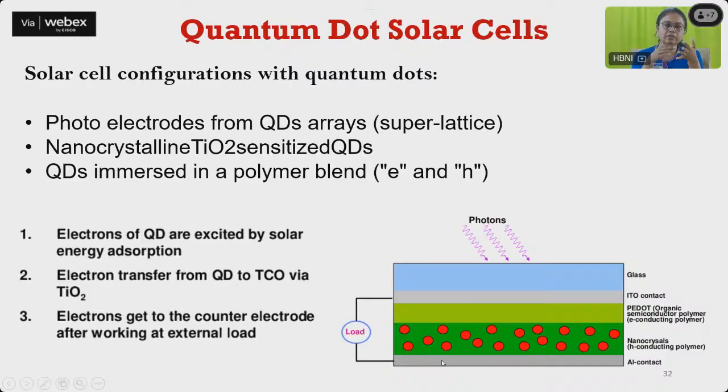So basically, whether we are talking about the dye sensitized, the perovskite or the quantum dot solar cells, these materials are the heart of the solar cell. So we are changing the heart, meaning we are changing the material which is acting as the absorber. If you remember, in the first slide we read that the absorber is the most important part of a solar cell. So we can use different kinds of absorber, and then there has to be an electron and hole carrier within the solar cell.